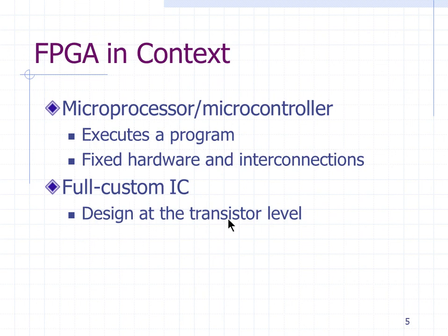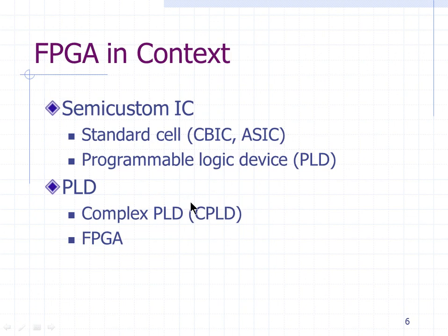So most of these designs, a lot of it is analog design, which is happening at CMOS level, and some other digital logic design where performance is extremely critical. So in such cases, the design is done at a transistor level, CMOS transistor level. That's called a full custom ASIC or a full custom IC design.